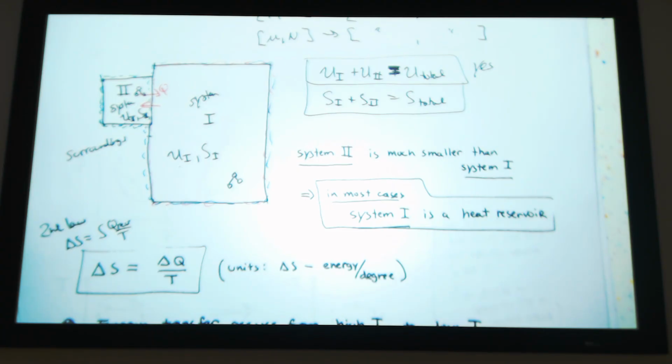But you know, it's this gray area, so really you have to see, can I change the temperature and pressure of my reservoir? So it's a judgment call. Yeah, but it's a judgment call, but you'd have to go through analysis, right? You'd have to define what is your level of acceptance. Is a 1% change in temperature and pressure good enough to consider my system a reservoir? Most cases I would say yes. In some scenarios 1% isn't good enough. In some cases 10% might be good enough. It's all based on the engineering.